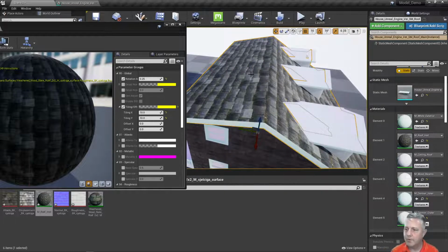So what we would have to do is open our project up in Maya, and apply material by using the faces method like I showed you in the materials video, actually 2 videos ago, using Maya materials, and we would put an additional material there which would give us an additional material slot here, and then we would be able to apply 2 different instances so that we could manipulate them separately.